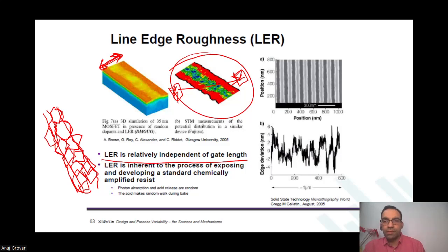Sir, the mask which you make, that will be made with the help of light, right? I think that's what he was mentioning before. Yeah, and that is what I'm clarifying. It is not about the mask at all. It is about the process of etching. It is about the chemical removal of the polysilicon that was extra there, so that only polysilicon wires remain. That is what I'm clarifying.